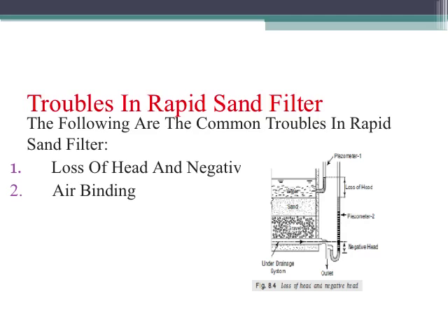The bottom sand then acts more or less like a vacuum, and the water is sucked through the filter media rather than getting filtered through it. The fall of mercury level in the piezometer inserted in the outlet pipe below the center line of the pipe will indicate the presence and extent of negative pressure created.